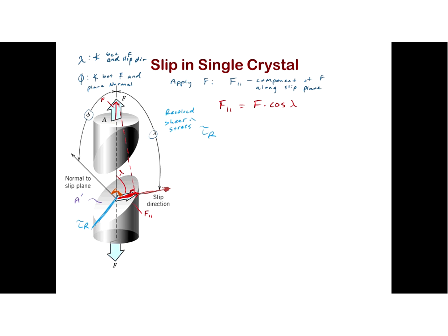And it's called the shear stress because the force is pushing parallel to the area that the plane of atoms is in, right? And not perpendicular. So even though we're tensile loading this thing, the overall sample, a component of it is in the slip direction within the plane, and that's causing the plane itself to be shear loaded. Does that sound okay? Sound reasonable? So tensile loading at the macro properties of the sample, in fact, resolves to shear loading along the plane. That's how planes slip in the sample. Questions about that? Seems fair enough, right? Reasonable?